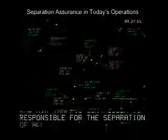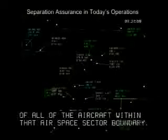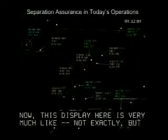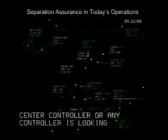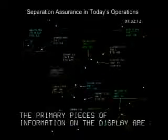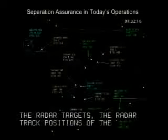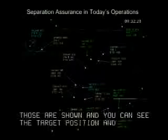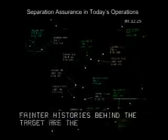Now, this display is very much like, not exactly, but very much like what a center controller or any controller is looking at. The primary pieces of information on the display are the radar targets, the radar track positions of the aircraft. You can see the target position, and then the fainter histories behind the target are the last 3 track histories of the particular aircraft.